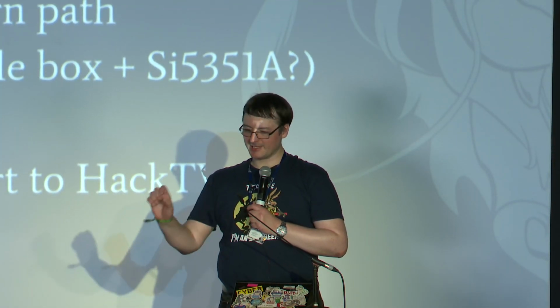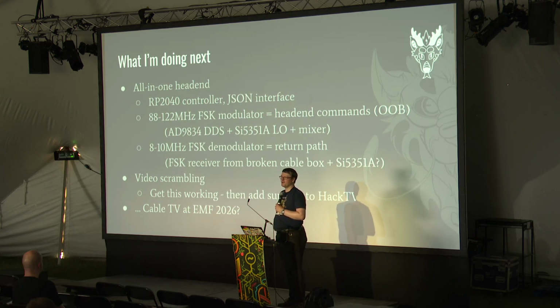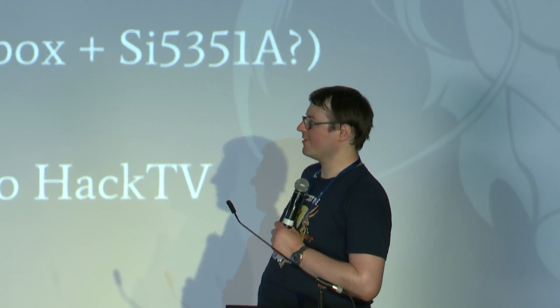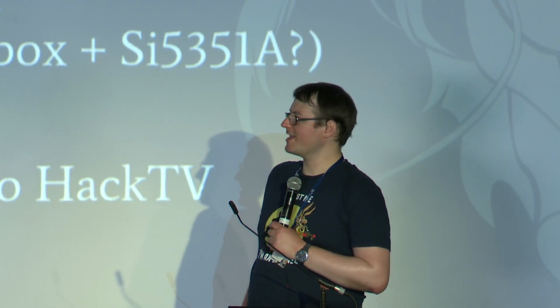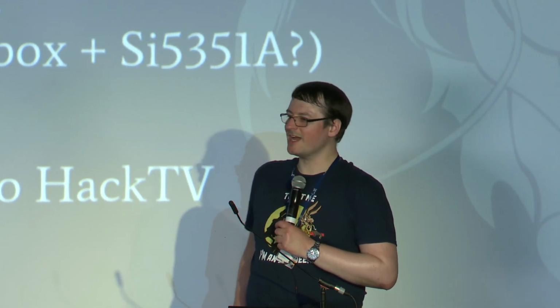And it guides you through sending them, and then you get a little data burst coming out of the data card, out of the ANIC. So I've got a little Arduino hooked up to it that can decode the commands and log them to a text file for me, and then it's just a matter of changing the parameters going into those commands in that test tool and writing down what happens and writing a program that can also generate them.